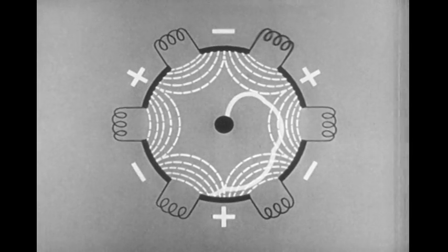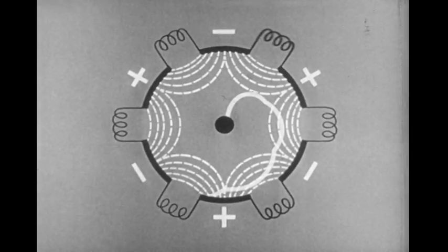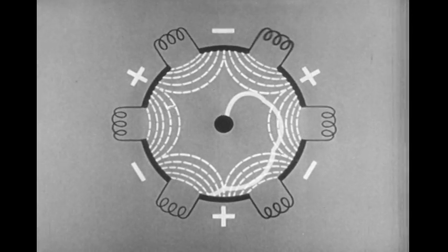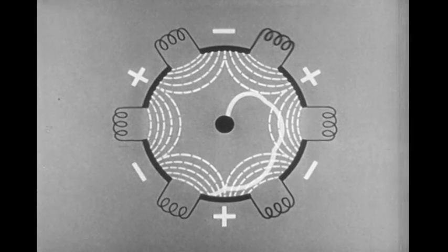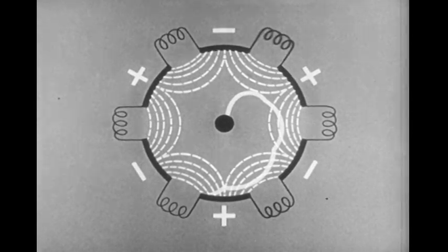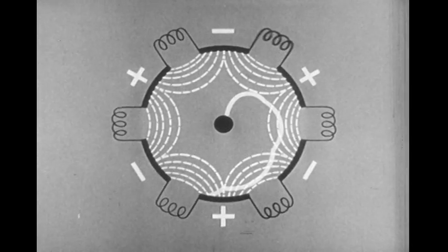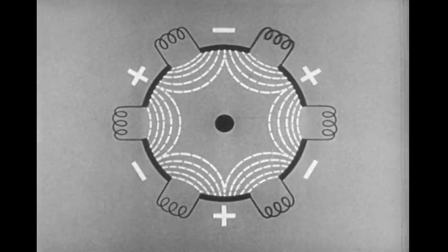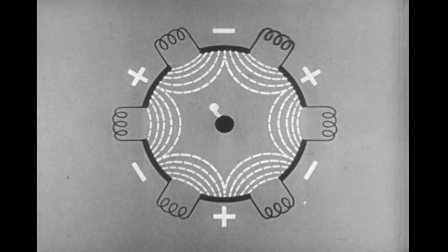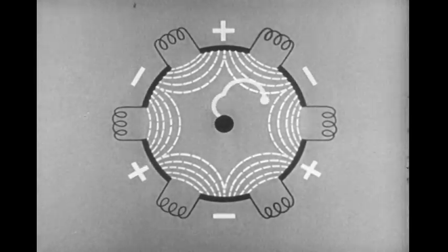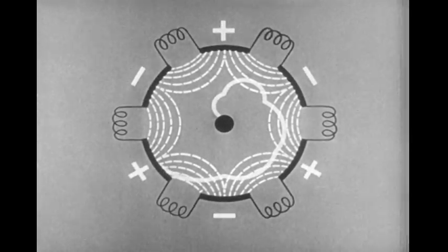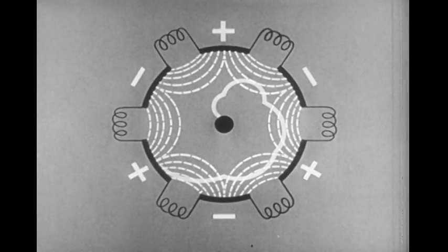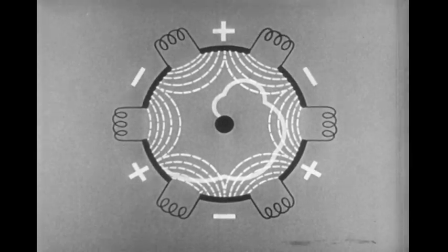By using a segmented anode, the electrons are made to work against an alternating electric field crosswise to the steady field. In this mode, the RF field gives the electron a finite transit time, which is 2 anode segments per cycle. But no definite time is set for the electrons to move from the cathode to the anode. It is this fact which makes it possible to build a magnetron large enough to deliver sufficient peak power to operate a radar system in the microwave region.